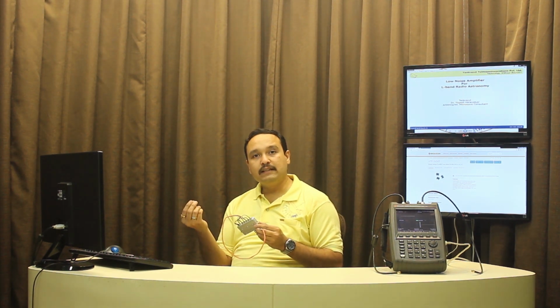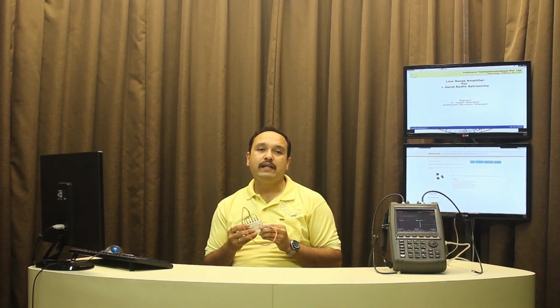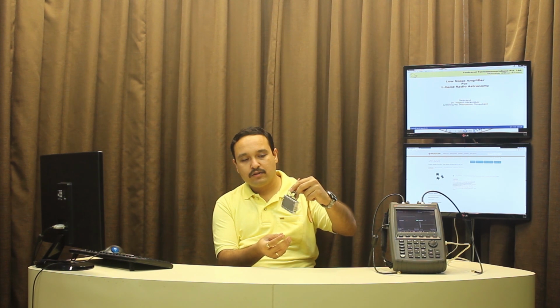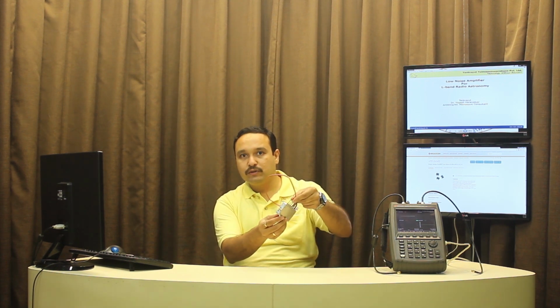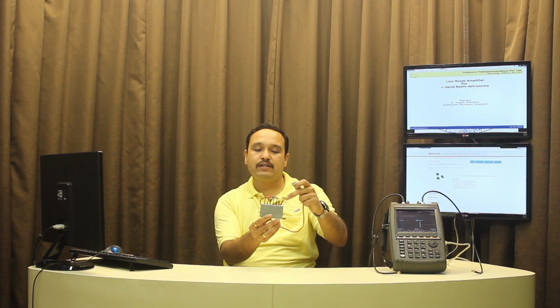Once we got our signals in the coaxial cables, the very next stage in any front-end system is an amplifier, and an amplifier with low noise. The unit which I have in my hand is one of my low noise amplifiers for L-band radio astronomy. As you can see, it's a completely packaged solution where you have an input which goes to the antenna, an output which could go to your subsequent RF system, and a bias with which you could bias the low noise amplifier and have very nice gain with very little noise added to it.